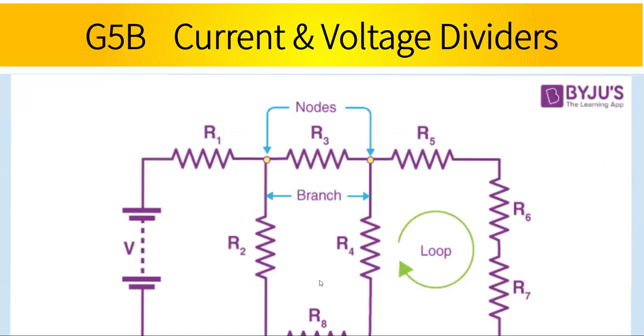So we have an example circuit here where it's got both nodes and loops. In the case of the node, you've got the current coming through R1 into this node, and then you've got a current through R2 and through R3, and those R2 and R3 currents are going to be equal to the current through R1. In the case of this loop, we've got a voltage across R5, R6, R7, which are in this direction, and a voltage across R4, which is positive.